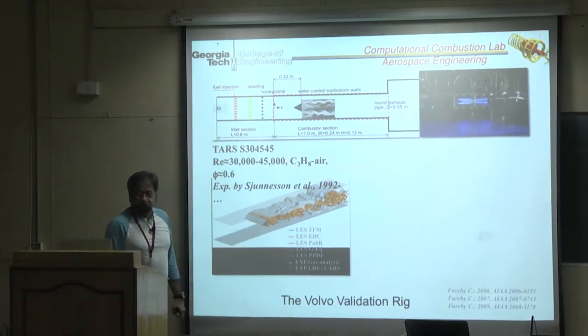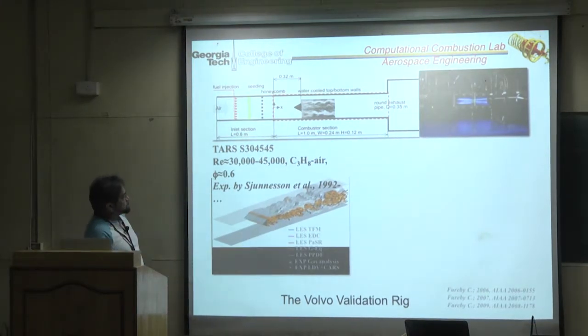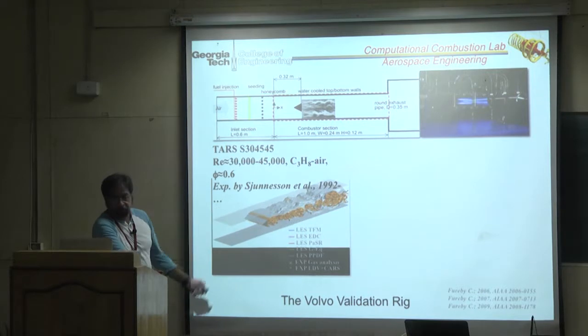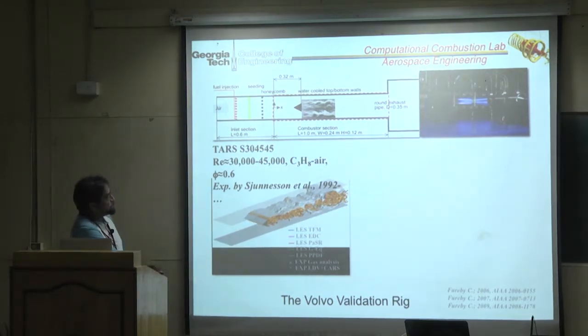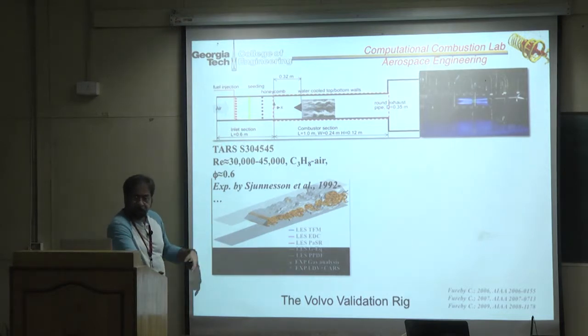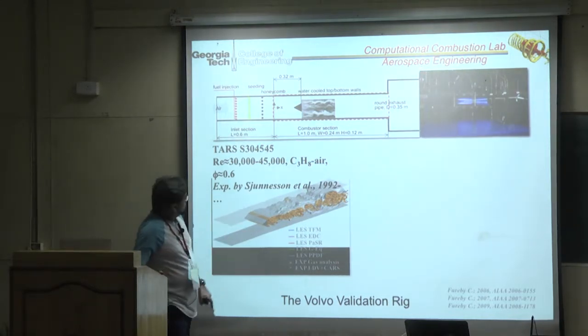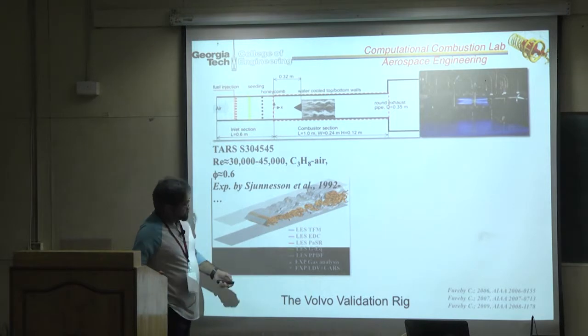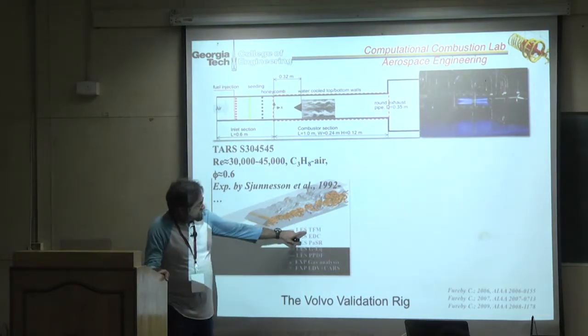That's an assumption because there's no proof, because as it happens, just like in any other experiment, nobody measured anything there, they measured stuff at the back. So numerically we have to assume it is premixed and run that, and then you get this flame structure at the back. You can see the image here, and there was non-reacting and reacting. In non-reacting, the fluid mechanics is very different to the reacting case, and this was work done by Fureby, and I've also done it.